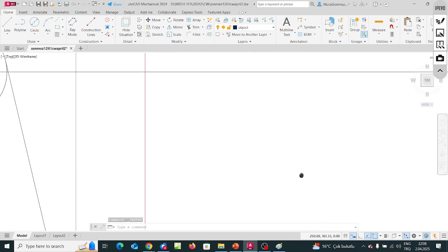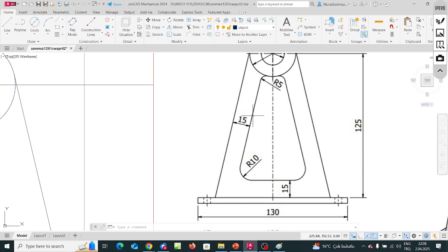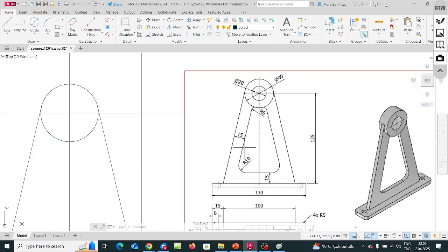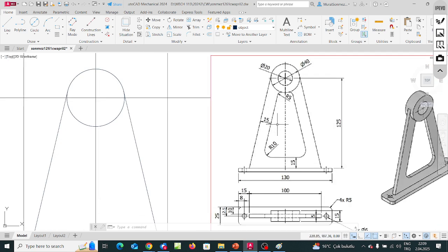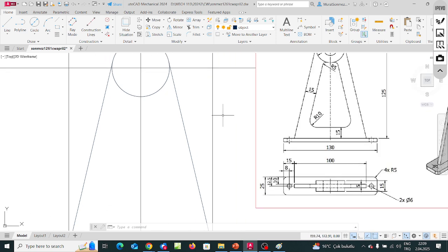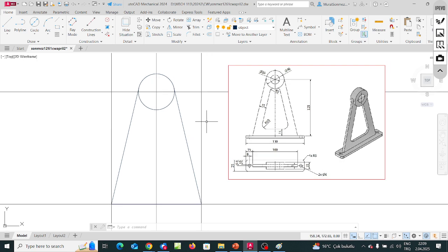And then I see I have this parallel line to this boundary, this parallel line, this parallel line. At this sketching stage, I'm going to omit these roundings, these fillets. To create a parallel line, it is recommended to use the offset copy technique.